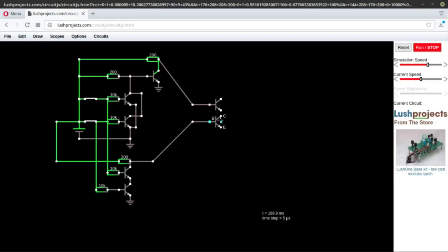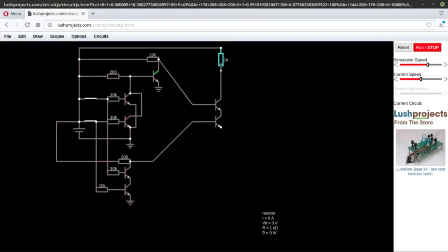Let's connect this to a transistor, and connect this to a transistor. We are basically making another NAND gate. Now if we connect the load here, we should get the XOR output here. Connect the ground here. This is an AND gate as in the previous video. When both of them are in the same state, this one turns off. When they are in alternating states, this one turns on.